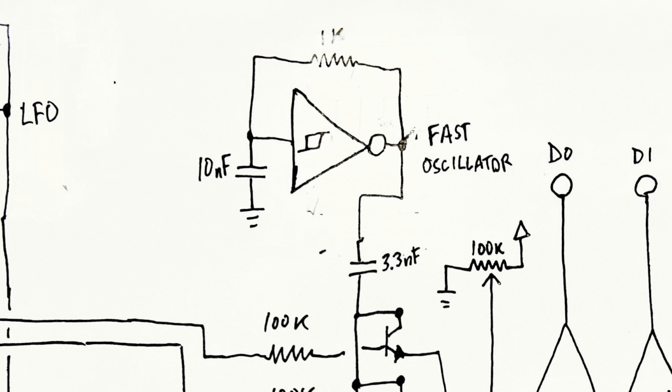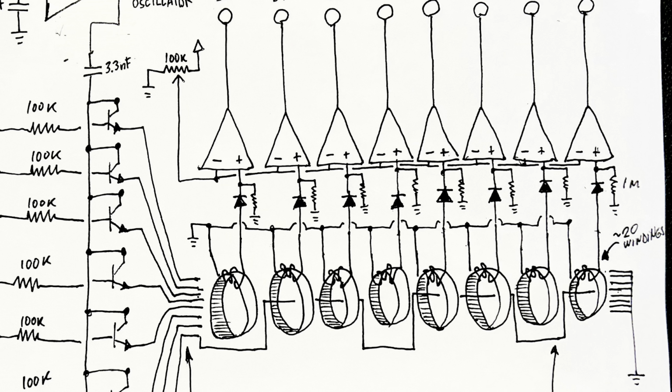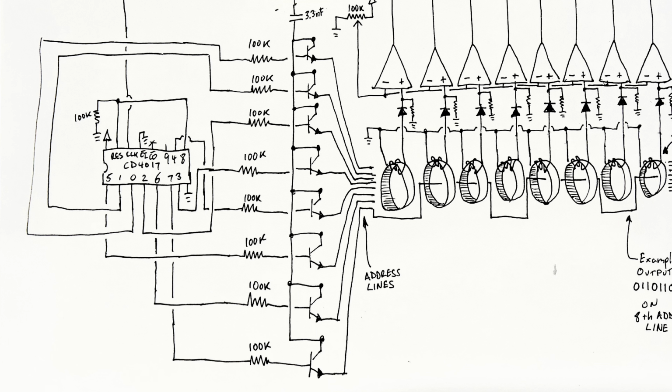And that signal was controlled by transistors, which were switched on and off by an external signal, and the output of the transistor was passed into or not through various ferrite cores, and the output signal of which was amplified out with an op-amp comparator circuit.